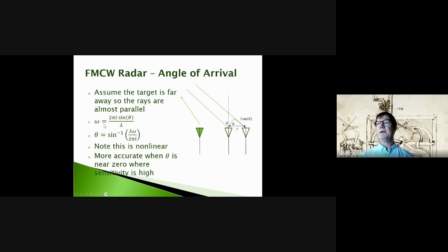So now this will ultimately give us this phase angle, again, similar to our velocity derivations, where we're going to look at what is the phase of the signal in this antenna relative to this antenna, right? So they're intercepting the same signal, but this one's traveled this incrementally small distance farther, right? And that is going to be represented by this 2 pi L, or the L times the sine of theta.